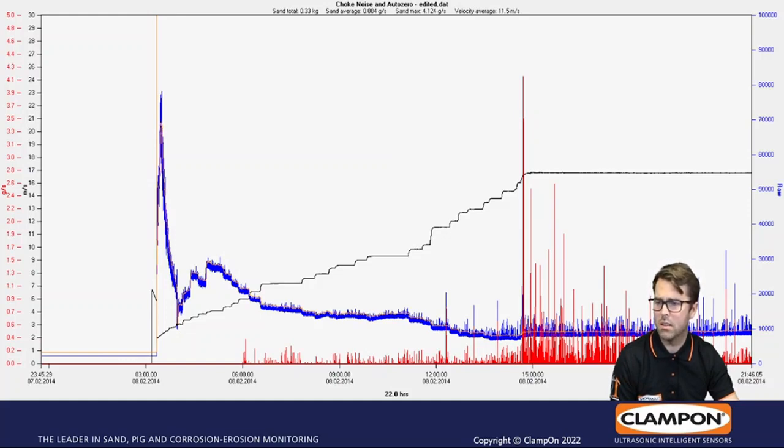So this is no sand, it's actually noise from the chalk. As you see here, the black line again is the calculated flow velocity, the blue color is the raw value, and as they chalk up, the noise from the chalk is reduced. And then when they came up to 60 meters per second here, we can see that they also have some small sand production. We're talking about 300-400 grams for the whole period here. So it's a very sensitive instrument.